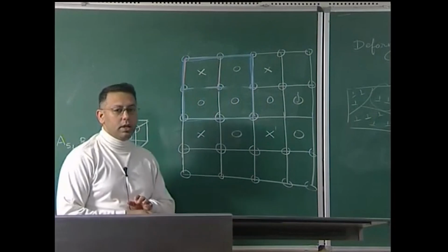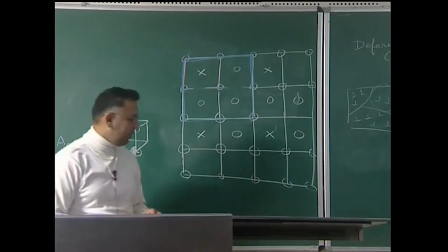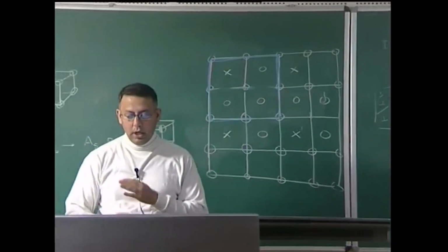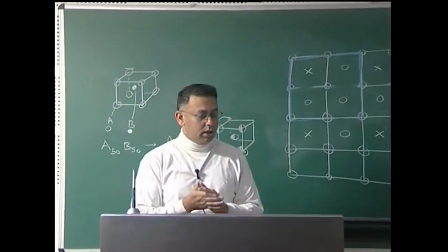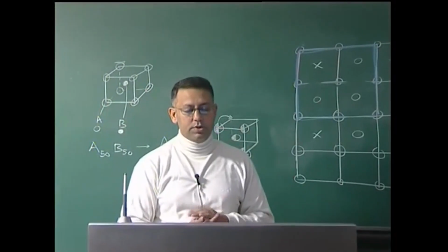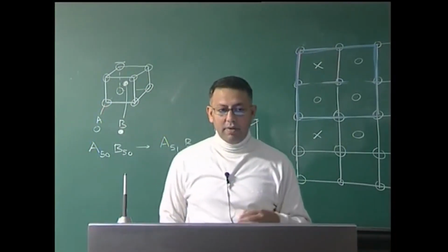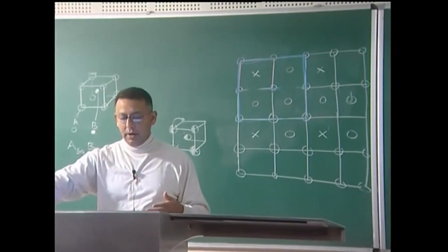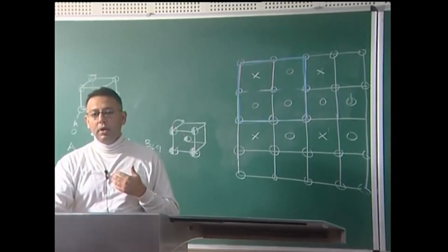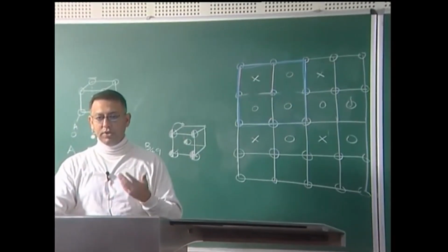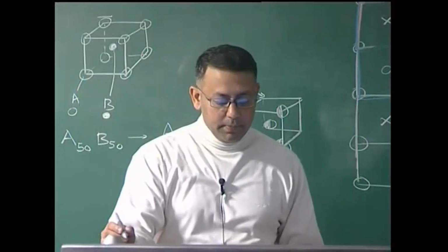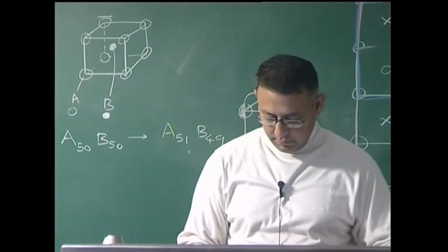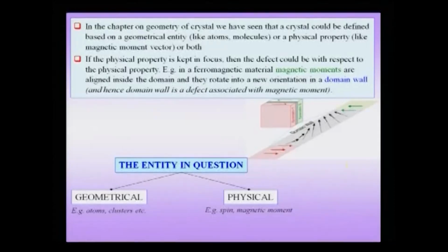Therefore, the lattice parameter and the symmetry at the fundamental level have been altered because of the ordering of vacancies, and that is why these ordered defects have a different role to play in the crystal as compared to a random defect. In other words, an ordered defect can actually become part of the structure, and therefore, it can alter the very definition of the crystal.